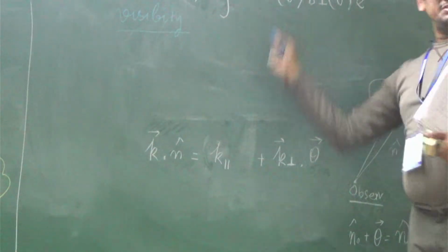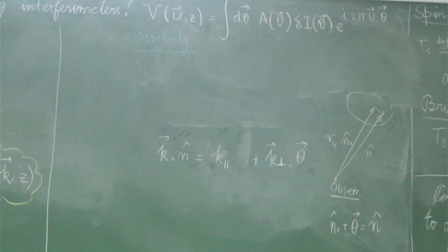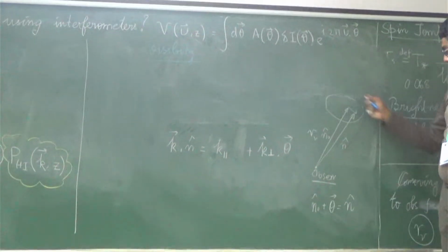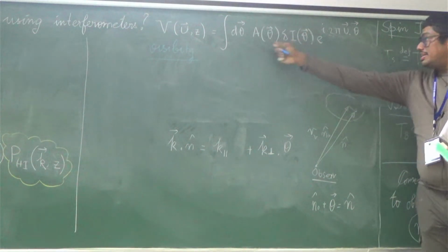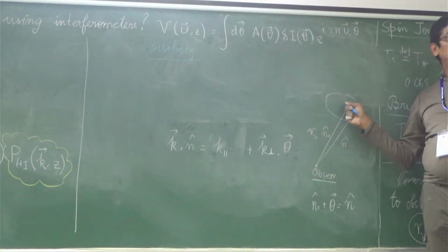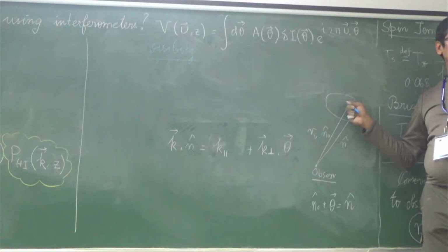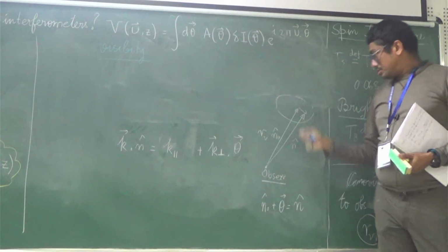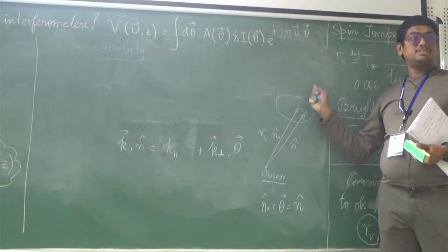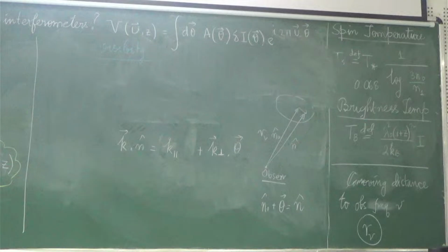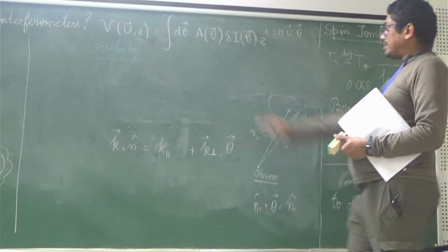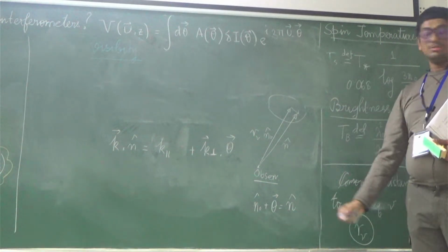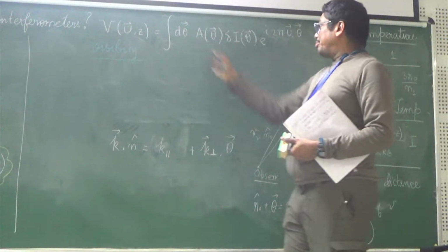But then I have this thing, which is what Toda was referring to as the beam. It is the directional sensitivity of the antenna. As we said, we can only see mostly in this field of view. A theta is a function which is 1 at the direction we are looking at. And then as theta increases, we can assume for the time being it is isotropic in theta, that is, as theta increases in all directions, it goes down. Eventually it falls to 0. It has a finite support, which basically tells you it goes to 0 at a finite extent of the field.